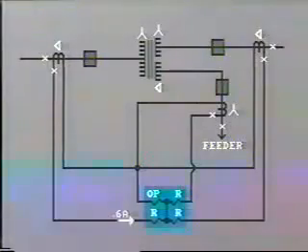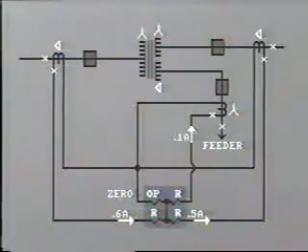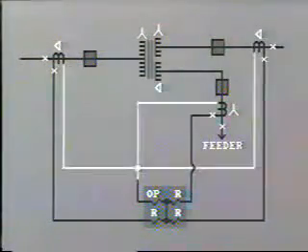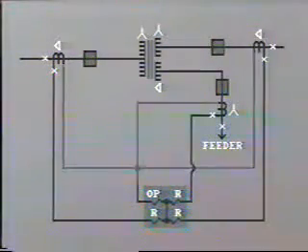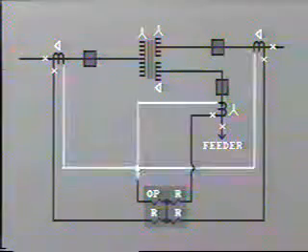Suppose we have, say, 0.6 amps in this first circuit, 0.5 in the second, and 0.1 in the tertiary. The current will flow like this, and as we can see, it still balances, and there is no flow of current through the operating coil. In studying these diagrams, usually these additional connections are left out for simplicity, but they are understood.